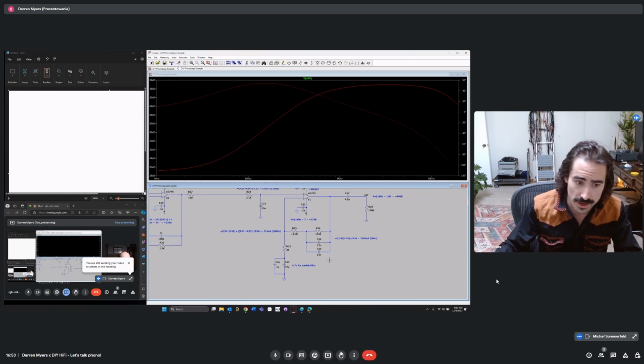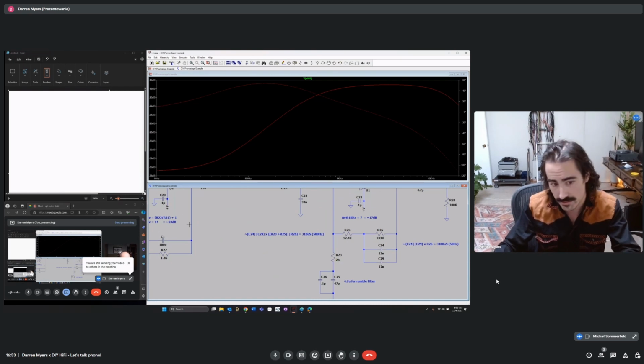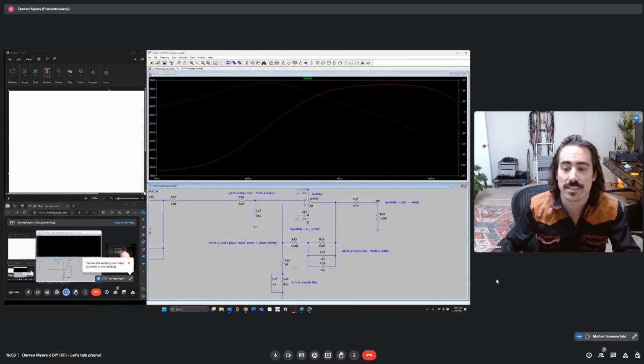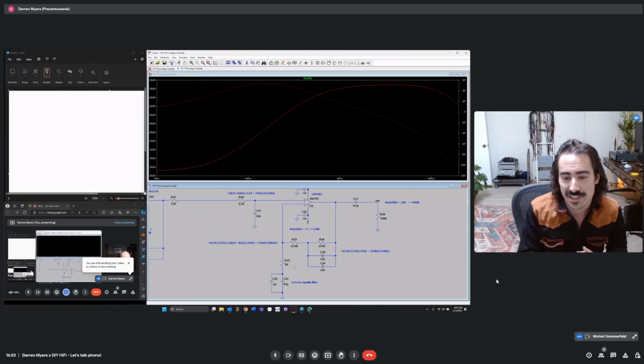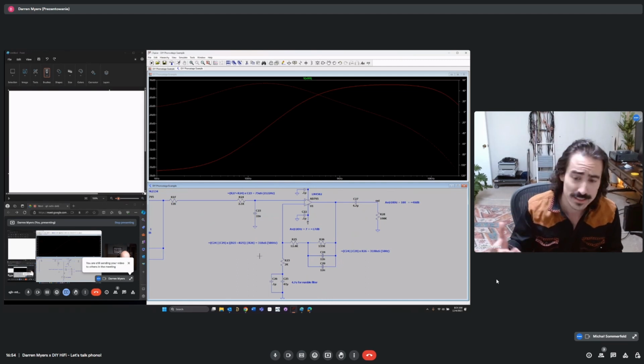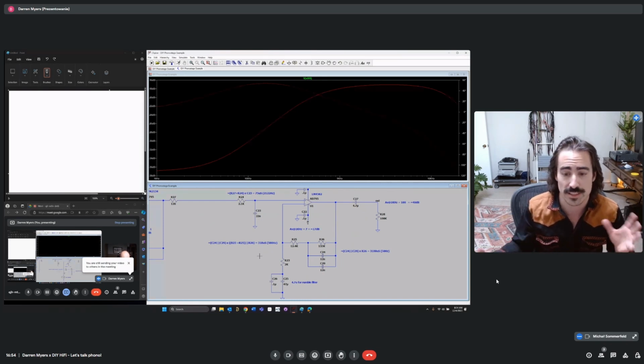So that means that you have RF, which is this resistance here, divided by R1, which is this resistance here, plus 1. And so that's how that value is created. But as you can see, when you change the gain, you change the pole. Or I'm pointing to a 0 right now. So, but you change the time constants. So you see now these are all interplayed, and this can get really complex very quickly.